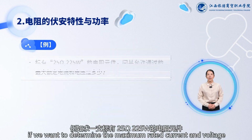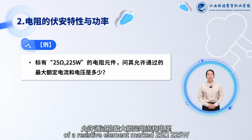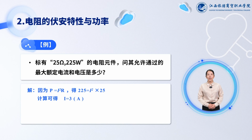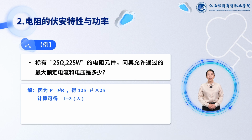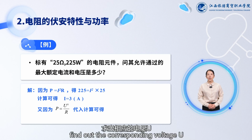For example, if we want to determine the maximum rated current and voltage of a resistance element marked 25 ohm, 225 W, we can analyze according to the formula of power. Use the formula P equals I squared R to calculate the current I. Then, according to the power formula, P equals U squared divided by R, find out the corresponding voltage U.